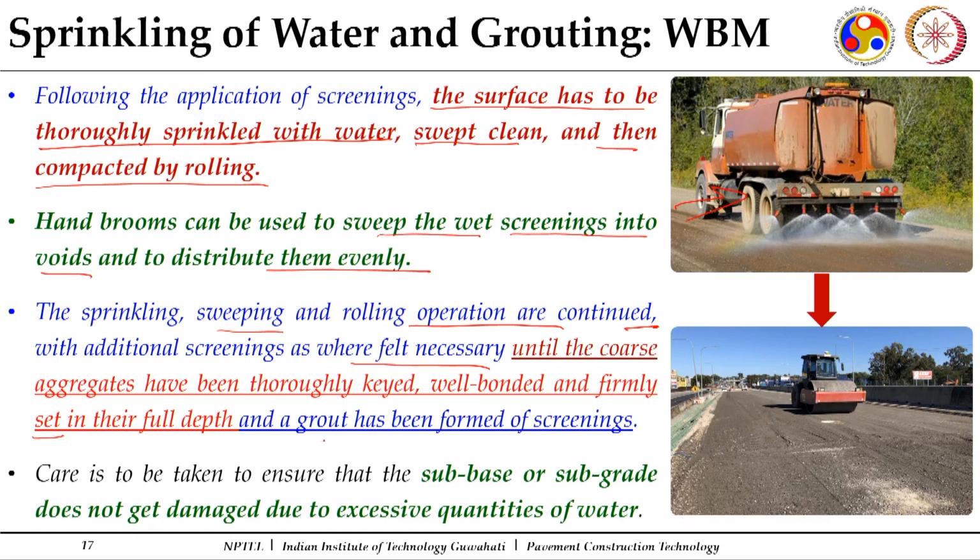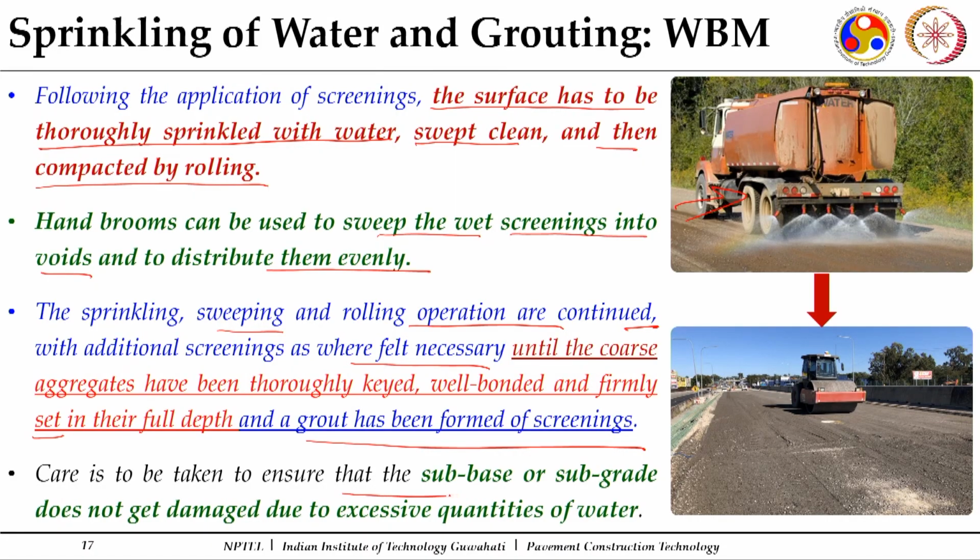And a grout has been formed of screening. Like a cementitious grout, this screening is acting as a grout to hold your coarse aggregates together. Care is to be taken to ensure that the subbase or subgrade does not get damaged due to excessive quantities of water.